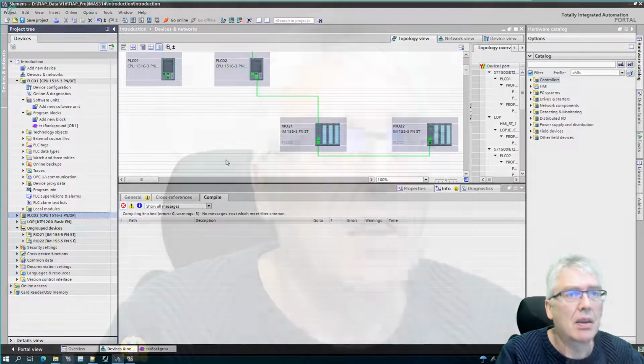Yes. So just to recap here, what's been done here is, first I had a PLC in my project. The first thing I did was I inserted an HMI panel and connected first the network, and then I had to make something called a connection. What kind of language are you going to use? You are going to use the HMI PLC language to talk to each other. And for these systems, they are built in. In firmware, the communication software is in the firmware, so they can talk to each other.